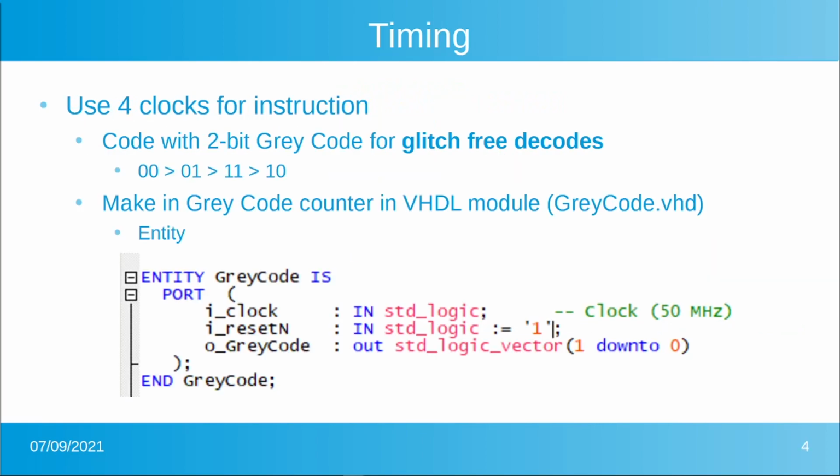So like I said, we're going to use the gray code counter for glitch-free decoding. And let's create the entity for that first. We'll give it its own file name, graycode.vhd. Try to stay obvious here for what it does. Same thing for the entity name. Remember, this appears 3 times, that gray code 3 times.